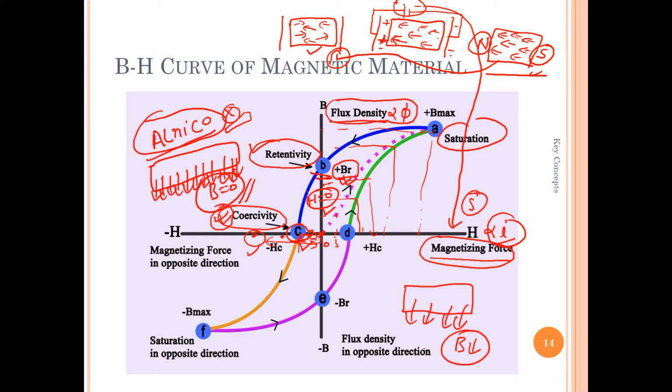So by the limitation of these two materials, we can't use them to design a motor for applications in which we require good thermal performance as well as good efficiency, with a high temperature and high power. Alnico delivers more power, but it doesn't support the high temperature rise.